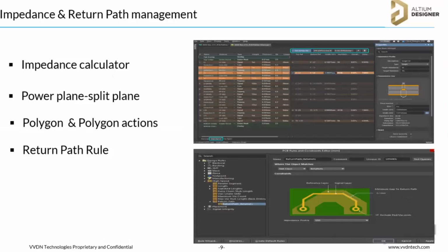Yeah. So we discussed we have to follow the impedance, but how can I calculate the impedance? In that sheet they mentioned I have to follow 50 ohm impedance, 90 ohm impedance, 100 ohm impedance, but how am I going to make sure that I'm following the proper impedances? So there is a formula to calculate that based on the track width, the copper thickness, the reference plane, the dielectric height and the nearby signal. So there are a lot of steps to calculate that.